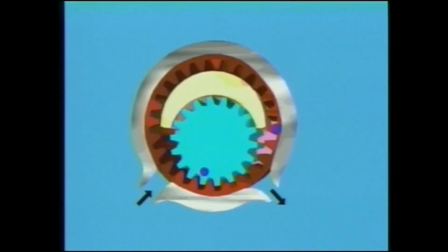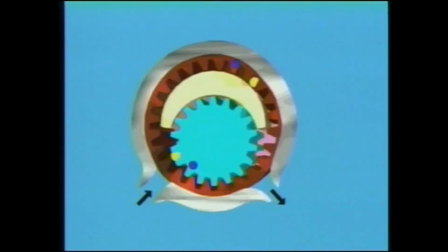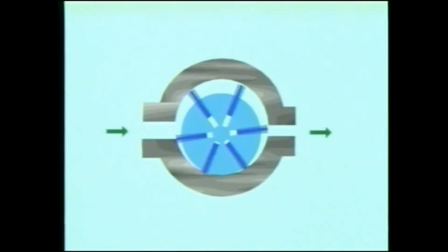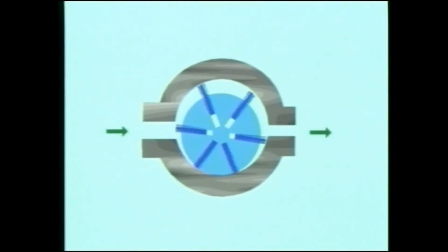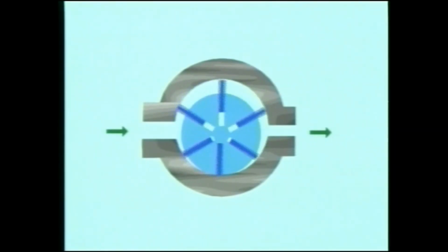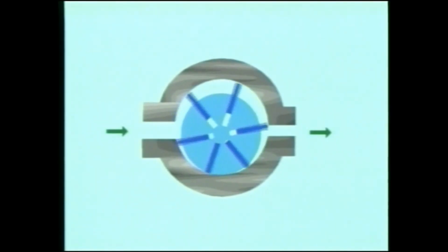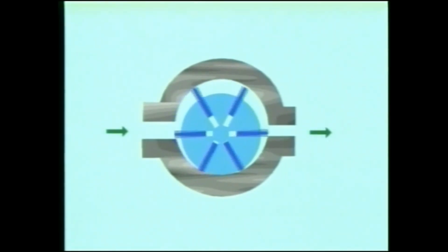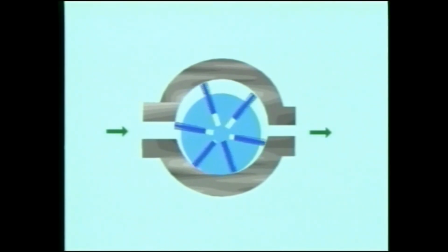There are two types of internal gear pumps. One type uses a crescent-shaped separator that traps the oil between the gear teeth. A second type of internal gear pump is the rotary version or gerotor pump. Another type of pump, the vane pump, uses small vanes instead of gear teeth to trap the oil. Because the vanes are either spring-loaded or free-floating, they self-compensate for wear.